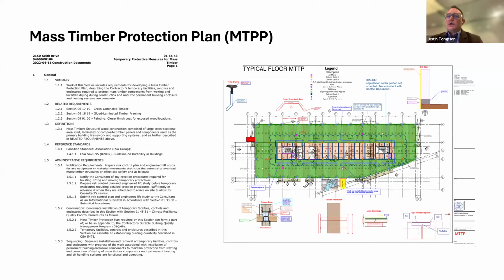from some of the areas within the floor plate to the windows when they're starting to do the membrane, starting to do the envelope on the exterior, and just how they're going to manage that. So they had protective measures to keep the rain off the floor, but that wasn't always possible. So then they had active squeegeeing into roof drains that they had put into the splines. Lindsay showed those channels where all the services run. So before the drywall and the channels were there, in the 3-ply splines they were able to cut holes and then put in a temporary roof drain and run a soft hose out of that, out through the window or out to the exterior, and let it drain outside of the building.